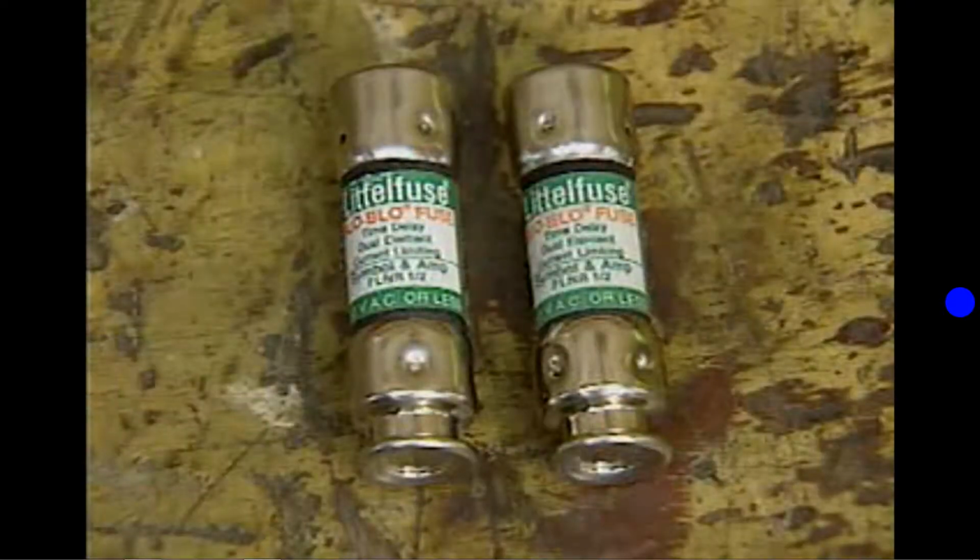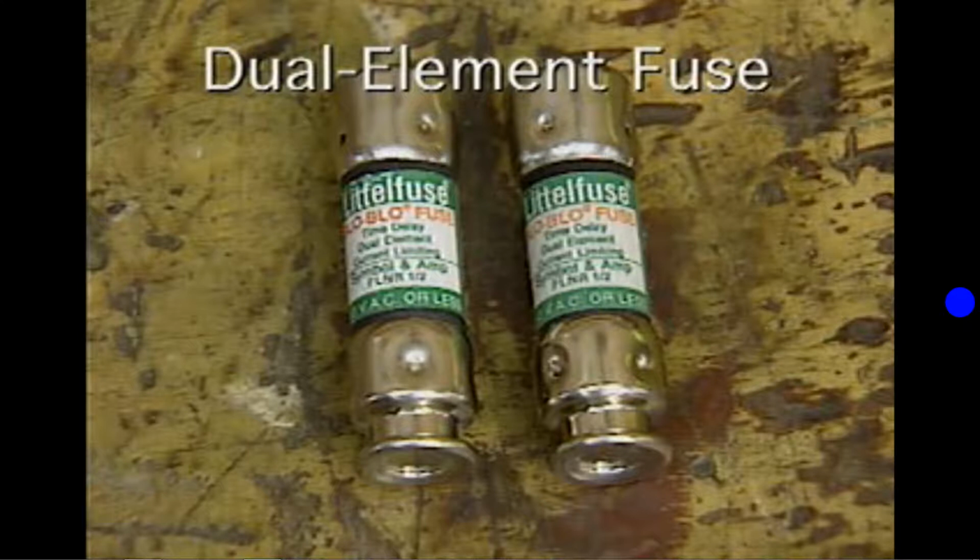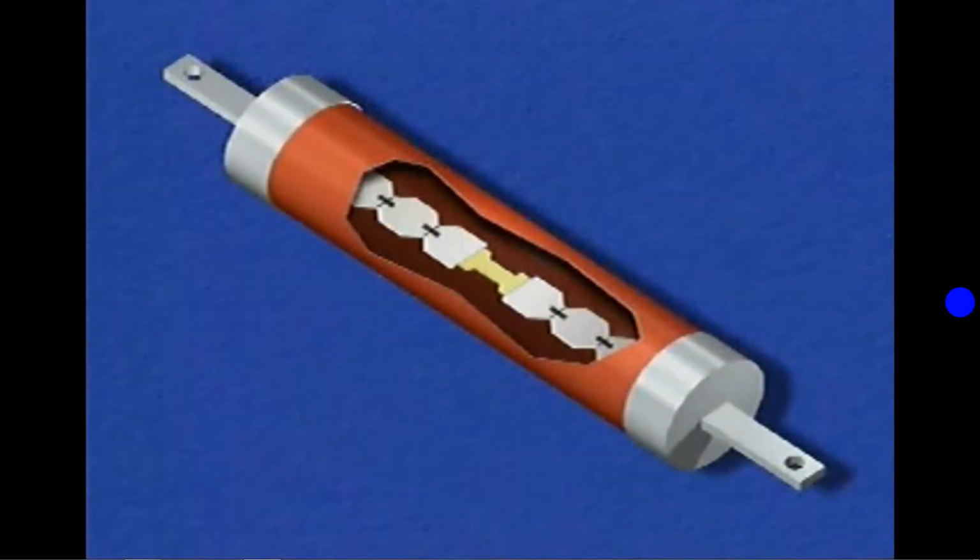A type of cartridge fuse that is specifically designed for motor branch circuit protection is a dual element fuse. A dual element fuse has two types of elements: short circuit and time delay. For example, this dual element fuse contains one fuse link that has two short circuit elements, one at each end of the fuse link, and a time delay element located in the middle of the fuse link.